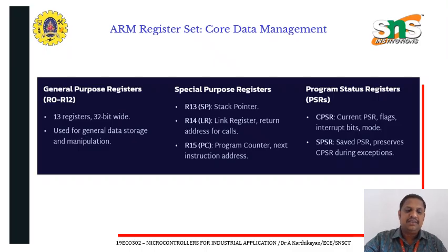This ARM register set is mainly used for core management. There are general purpose registers, special purpose registers, and the program status registers, that is the PSRs. We have R0 to R12, that is 13 registers, each 32 bits wide, used for general purpose data storage and manipulation.